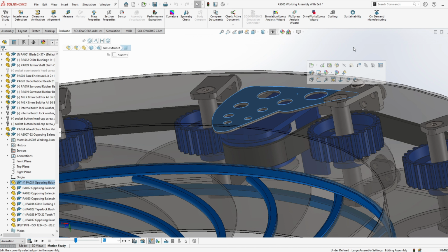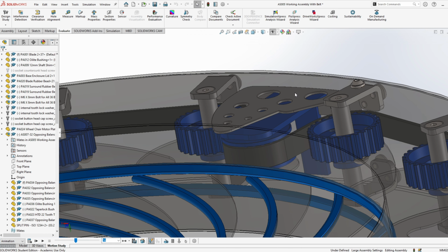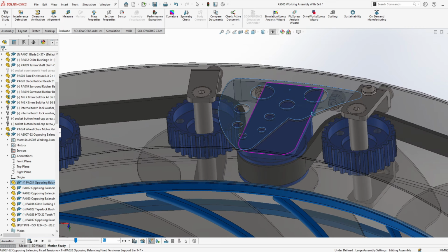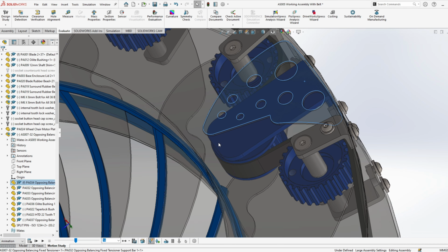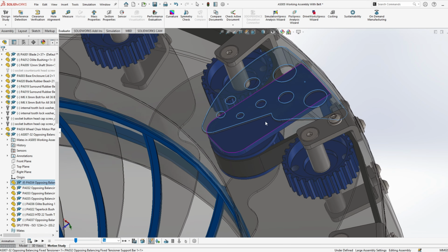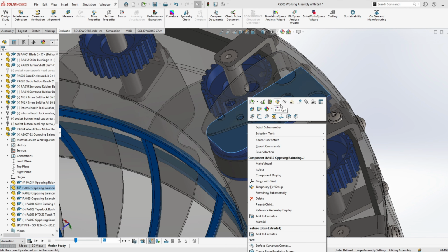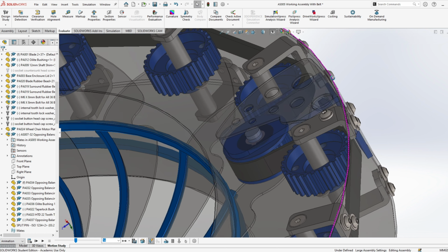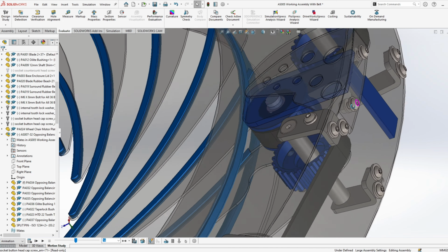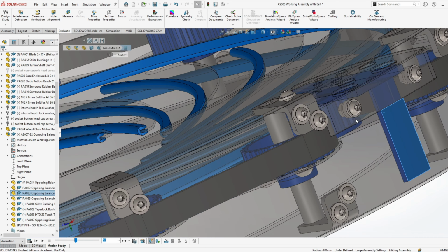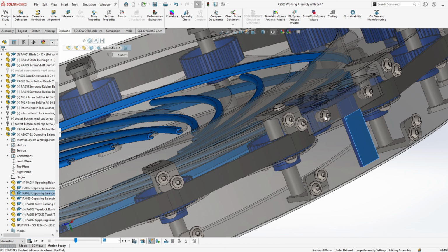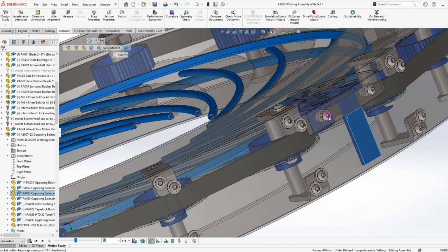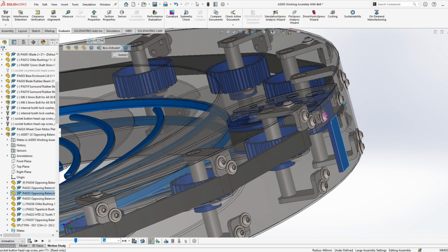So I'm going to set this plate to transparent here to just get a look at what's underneath exactly. So we have this 6mm plate here, which is about 100mm long, 50mm wide. I will set it transparent too, to show the shaft. We have the shaft, which is welded directly into the stainless steel plate. We also have another stainless steel plate which goes down the back to support it. We have these two M6 bolts, domed head bolts, which fix the tensioner to the base enclosure.